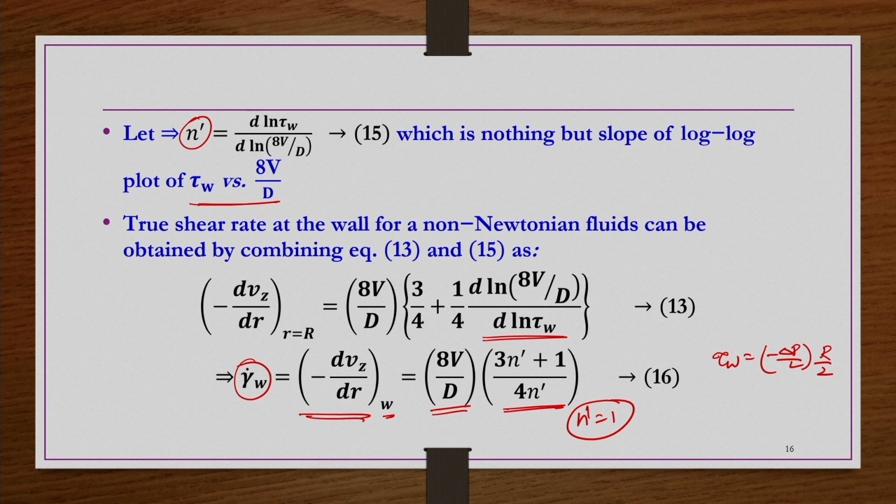So, what we understand is, if you have the pressure drop and the average velocity from your capillary rheometer experiments, you can change the pressure drop and get different volumetric flow rates. So, then you can get Q versus delta P information, with enough number of experiments, and then Q you convert in terms of V average, or V, as we are using the symbol V here.